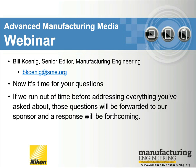And our last question, what is the accuracy of the machine? Yep. So again, the overall accuracy of the machine, depending on the size, is somewhere between 2 plus 8L over 1,000 up to 3 plus 6L over 1,000. So an overall estimation, you could say, maybe right around 4, 5, 6 microns to the volume of the machine.